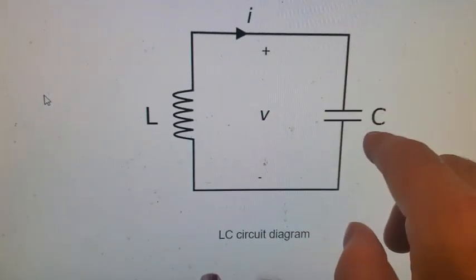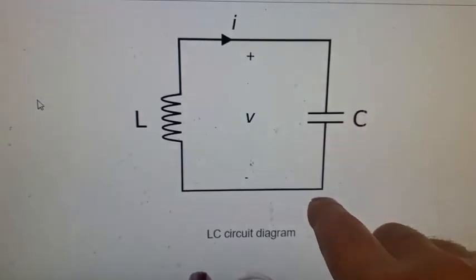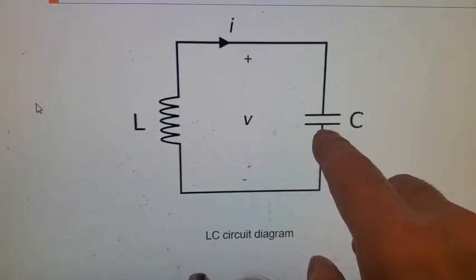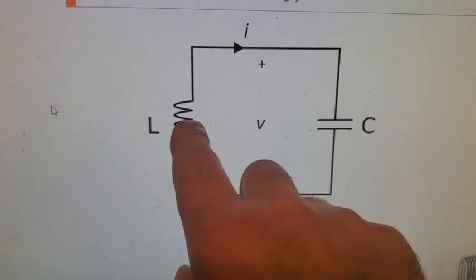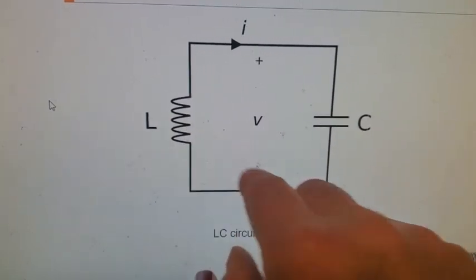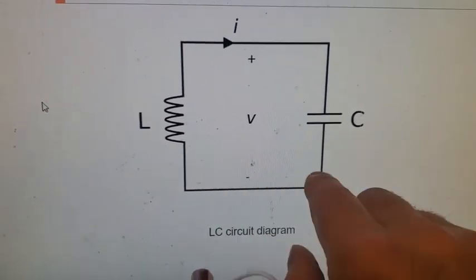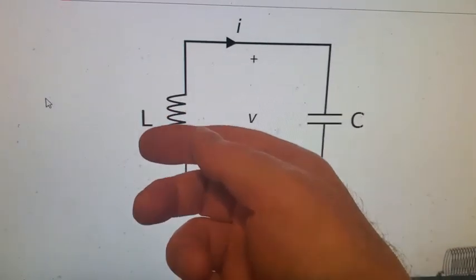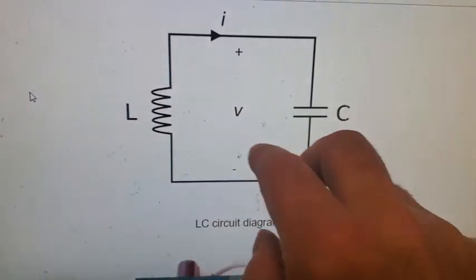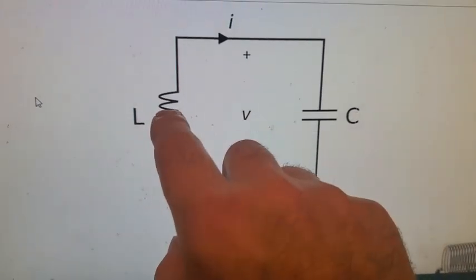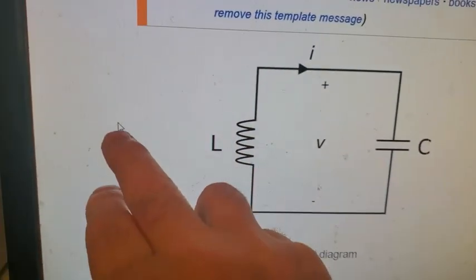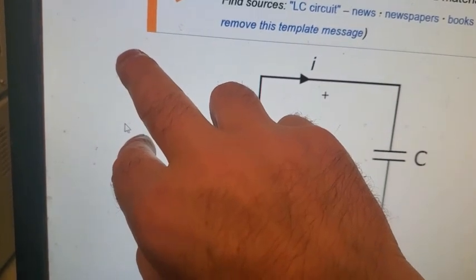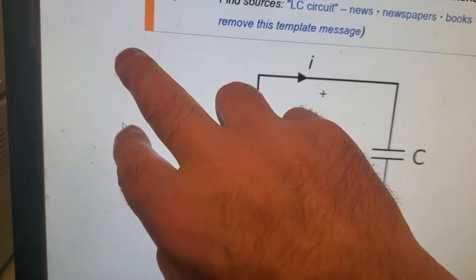So you have this thing going 10, let's say -9, 8. When the capacitor gets to 0, when it goes from 10 to 0, is where you have the highest field strength. Now, when it goes from 0 to -1, current's still flowing here, but it's flowing less strongly, and so there the inductor is already beginning to weaken. So when this goes to 0, if you open it right there, that's where you get the best transformation of voltage and your maximal pulse into another cap.